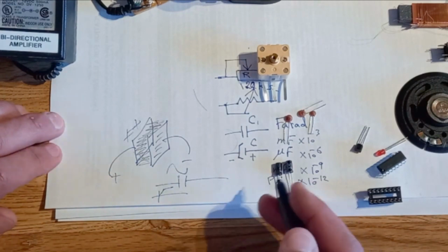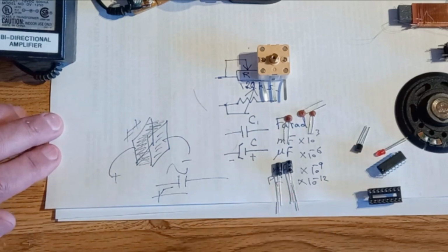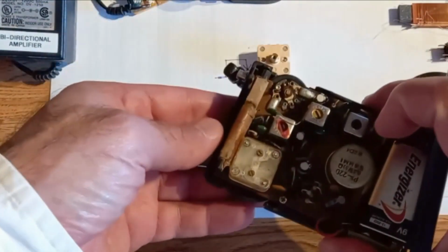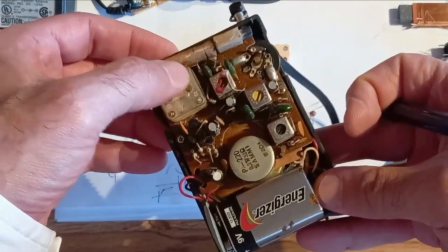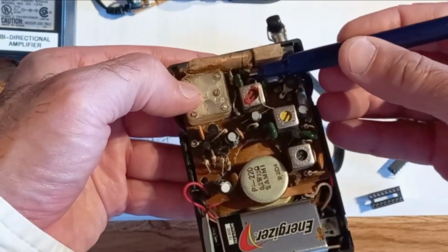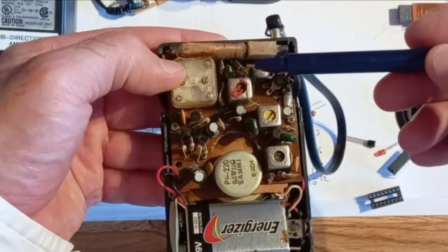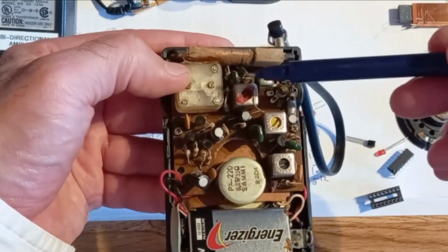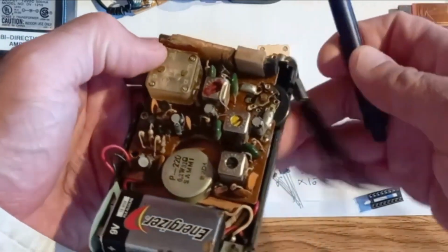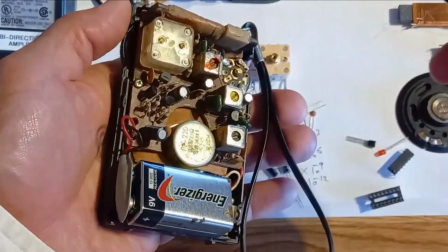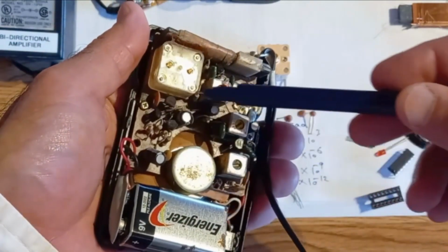Examples can be in radio tuners, same as I just mentioned in that radio again. This variable capacitor is actually for tuning, but there are other fixed capacitors here that are used, polymer capacitors, electrolytic capacitors. Some of them are used for filtering and some for charging and discharging energy into the circuit to cause that amplification that you need in the amplifier part of the circuit.